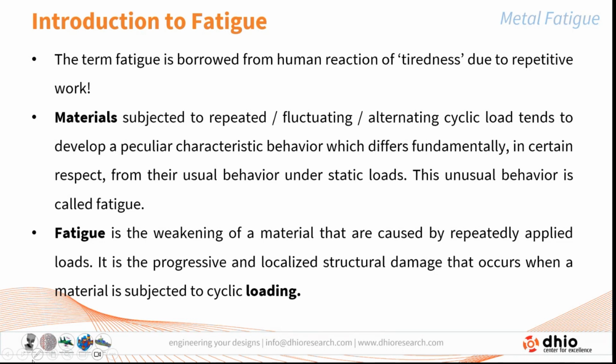When I say repeated, it may be the same load which is repeating. Let us take an example of a tensile load acting from 0 to 50 Newton and again coming back to 0 and again going back to 50. That is called a repeated loading.